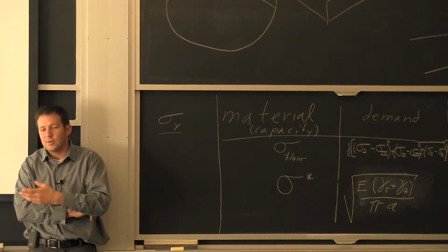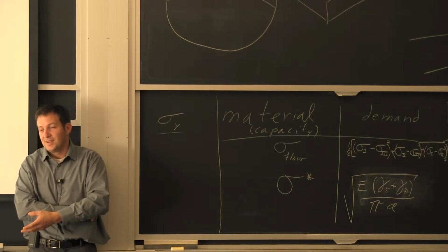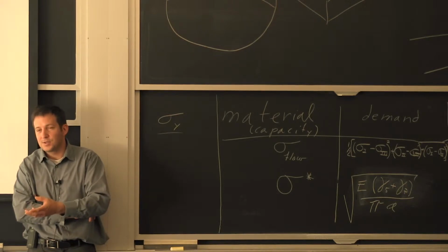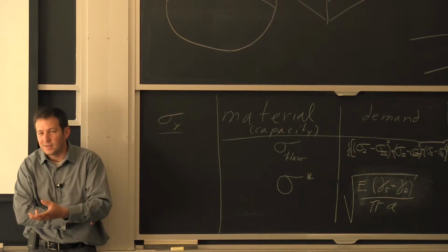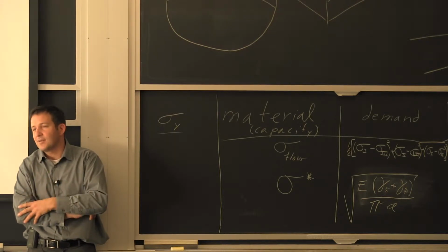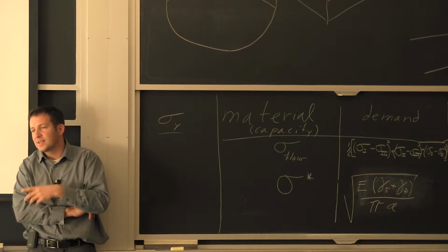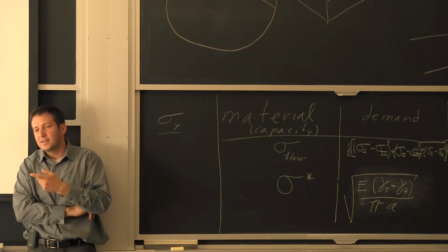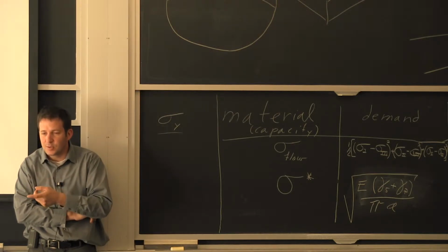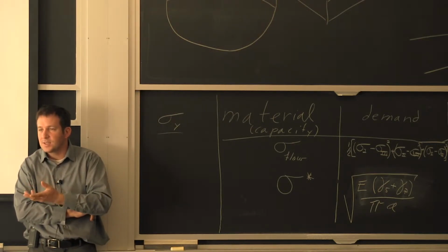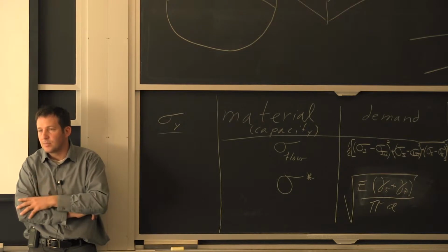And therefore, you probably have to go to maybe, instead of being 40% of the yield strength, 30% of the yield strength, which is what the math tells us, until you really don't have anything going on in terms of back and forth plasticity. The back and forth plasticity is really what kills the material in terms of growing voids. If you can stay elastic locally, then you're fine.